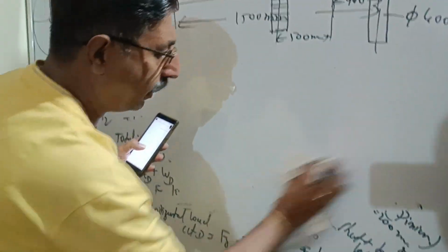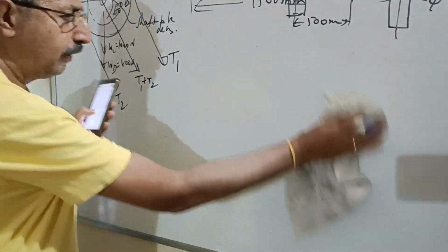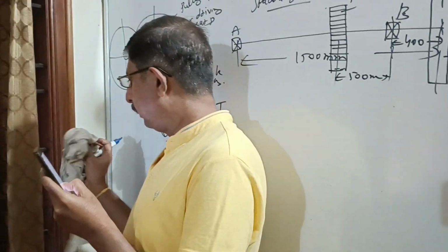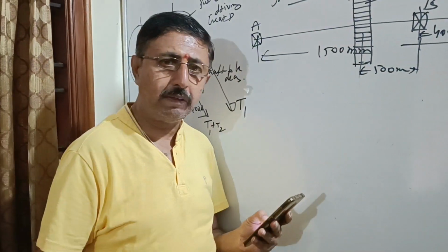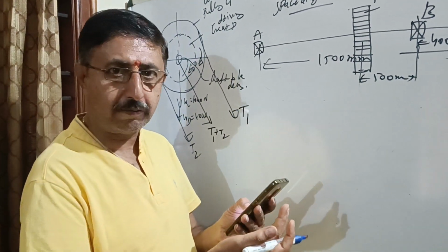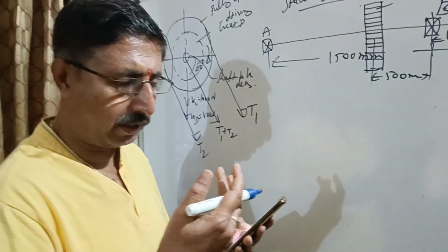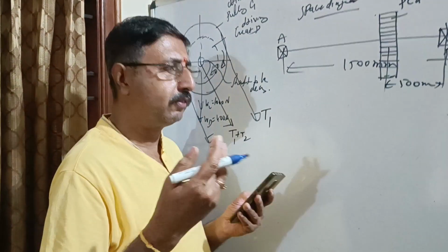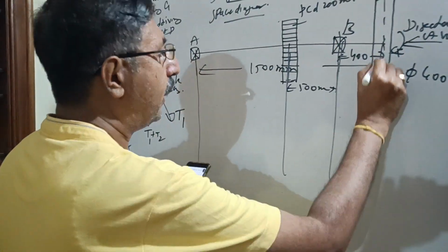So this is over now. We have analyzed pulley C and gear D. I hope you understood how to analyze pulley C. Pulley C is a driven pulley because the power has been received by the shaft through that pulley. Whatever pulley is mounted on the shaft is a driven pulley. Now whatever power has been received by the shaft will be delivered by means of a gear. So the gear mounted on the shaft is a driving gear. Now let us draw the loading diagram.